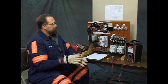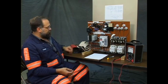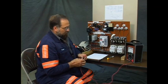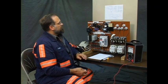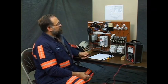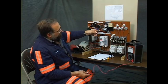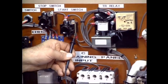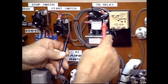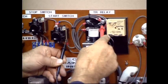Now we believe that TR contact is going in. We heard it. It may not really be made though. Let's check things out. The contact could be made and the wire could still be interrupted. So I'm going to read that part of the circuit first. I'm going to read from the load side of the start switch, load side meaning toward the work, to the TR mercury tube, line side of the TR mercury tube.